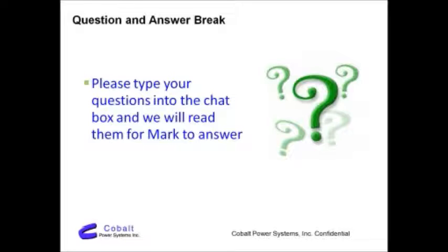Now, in terms of where to put the inverter, you can put the inverter at the array, in which case the DC run is very short and the AC run is long, or you can put the inverter at the house, in which case the DC run is long and the AC is short. It's generally better to have a long DC run because the DC voltage is higher. The DC voltage is in the range of 300 to 500 volts DC.